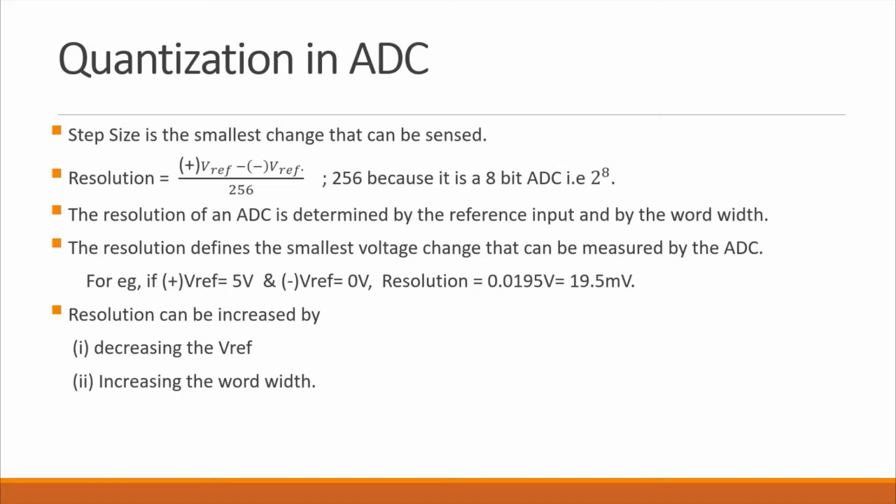But still, for my application, even if there is a small change in the temperature, I want my system to identify it. That is called your resolution: the smallest change, even if it is there, that should be identified by the machine. So that is my resolution. When you're talking about an ADC, you always have to first ask yourself, what is the resolution required for my application?